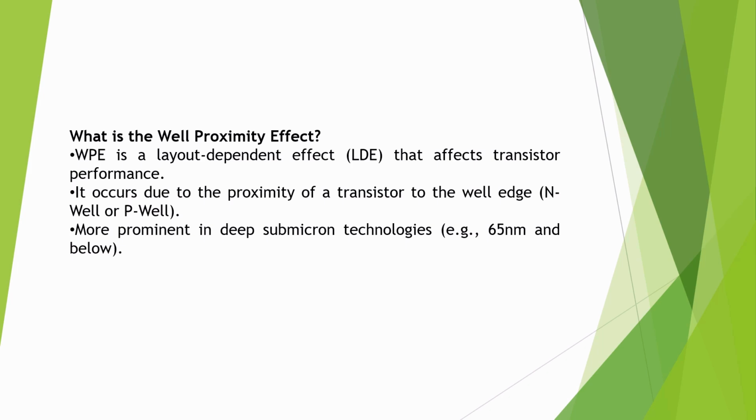WPE is a layout dependent effect that affects transistor performance. It occurs due to the proximity of the transistor to the well edge, N well or P well. It is more prominent in deep submicron technology. It means it is dominant in 65 nm and below technology nodes. So WPE is generally a layout dependent effect.